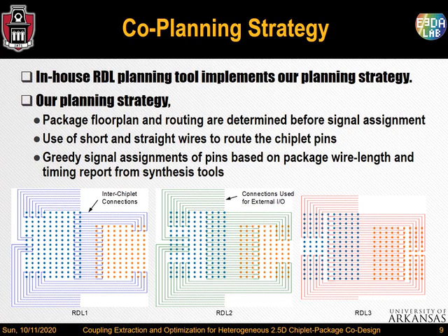Based on this routing and the timing report generated through analysis on the gate level netlist, the signal assignment of the chiplet pins is performed. This is done following a greedy approach so that slower signals are assigned to the shorter package wires.